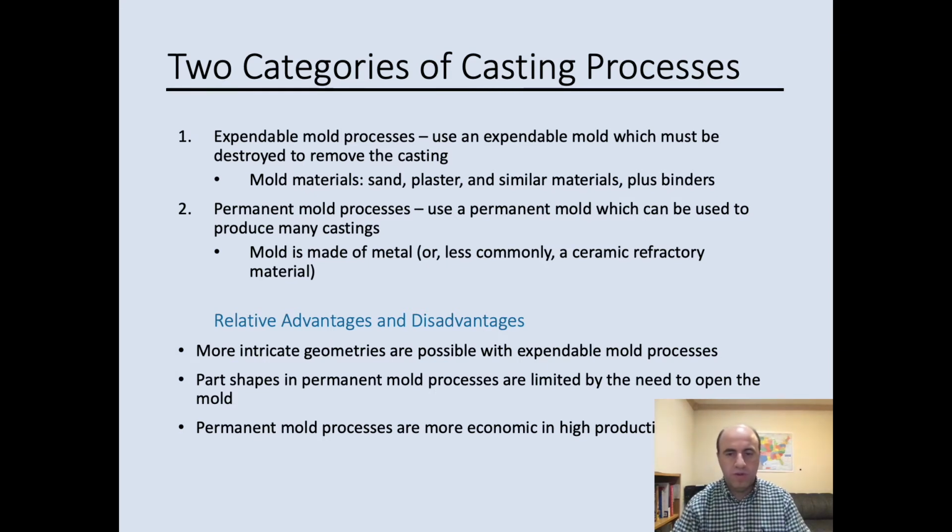The permanent mold process is more economical when we have large production, since we don't need to change the mold, so we will keep the mold for many days, for many parts.